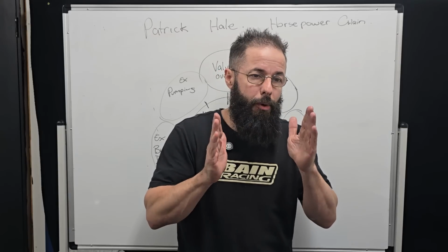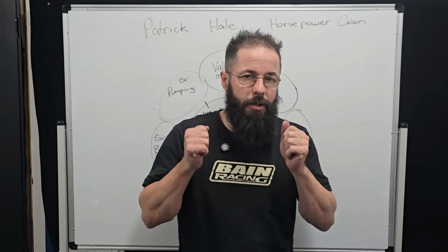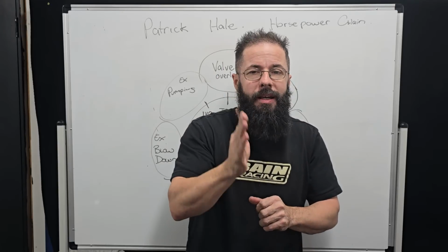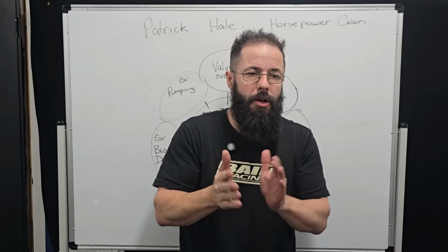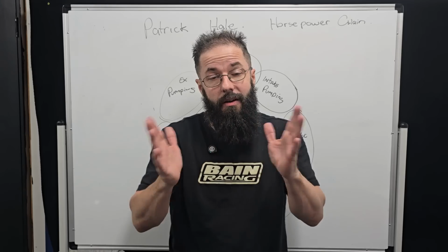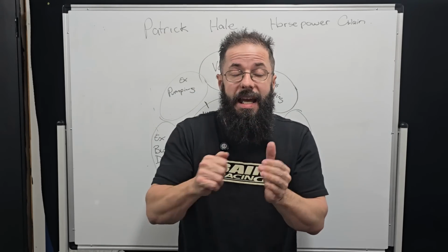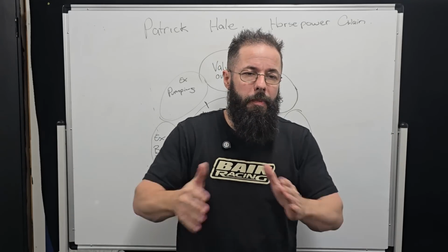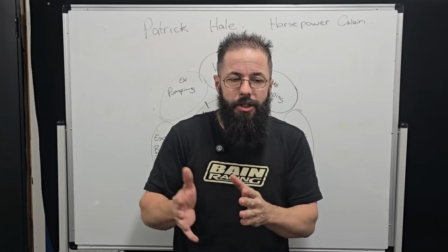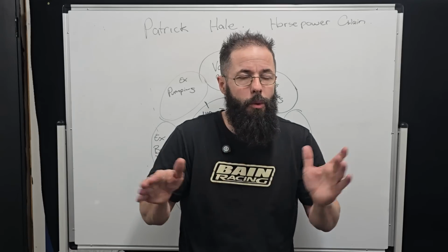And also the RPM point you're targeting, because one LSA isn't right for all RPM. Just like a camshaft only works at 7,821. Wherever the point is, each side of that is always a compromise. That's why variable cam timing is such a blessing, because now we can vary LSA and timing and duration and stuff like that, so that we can carry torque longer, have a wider torque band, have a wider power or horsepower band as well. Because generally in our race engines, our power band is 1500 RPM, 2000 with EFI. It's not very wide at all.